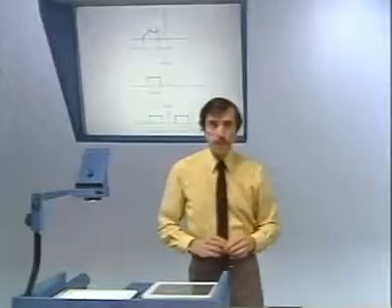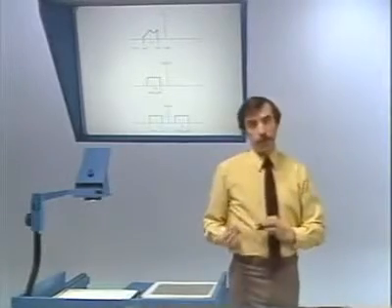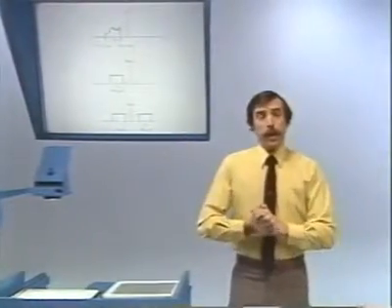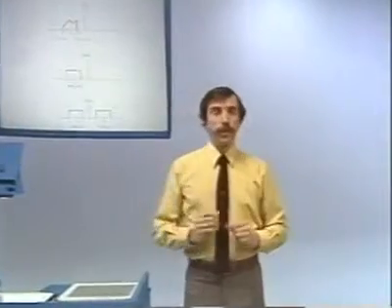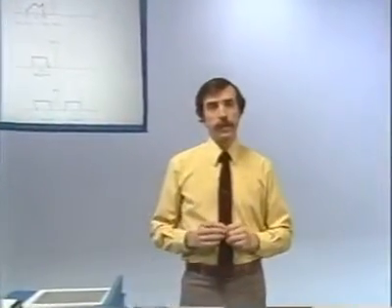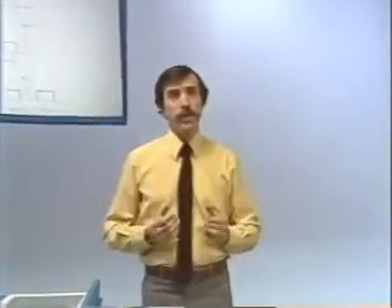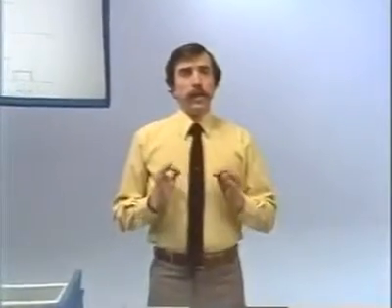Now, just to reiterate a point that I made earlier, the question, of course, is why would you go to this trouble? Why not just build a bandpass filter? And one of the reasons is that it's often much easier to build a fixed filter, a filter with a fixed center frequency, for example, a low-pass filter, than it is to build a filter that has variable components in it so that when you vary them, the filter center frequency shifts around.